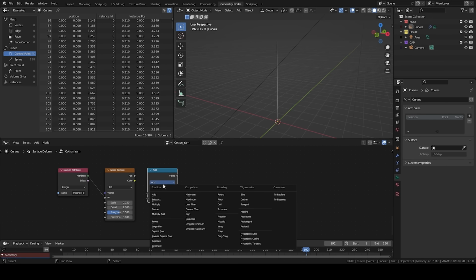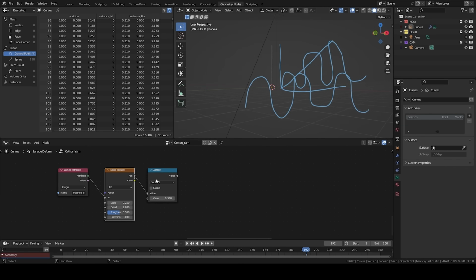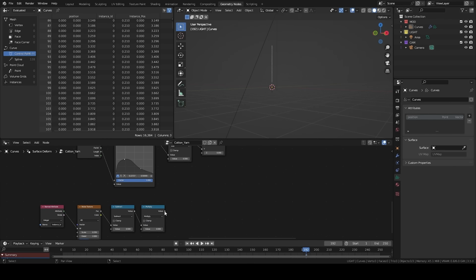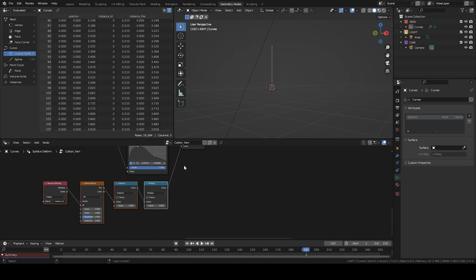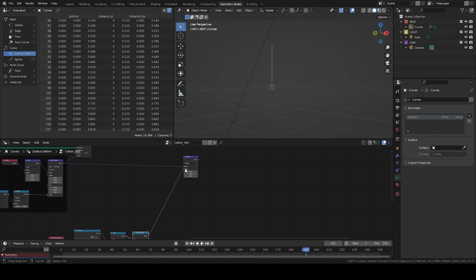It'll be fine. Math node that I set to subtract to allow my noise to finally go from 0 to 1. If we visualize it on a curve, it really goes from 0 to 1. At least it oscillates like that. I want it to hover around 0, so I'm going to remove 0.5 from it. Behind it, I'm going to put a math node to give amplitude. It will be just to give a small coefficient if we ever need it, to give more noise or not. I'm going to plug this output into the multiply node that we created just before.